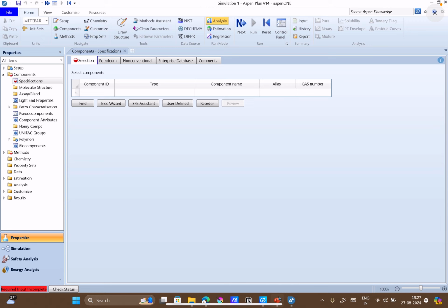Number of tie lines is getting changed. So, just a minute. See, mole fraction of MIBK is 0.35 and mole fraction of water is 0.64 at 361 Kelvin. Can you go to the ternary one part? There it will be same. The azeotrope 0.35, it's exactly same.